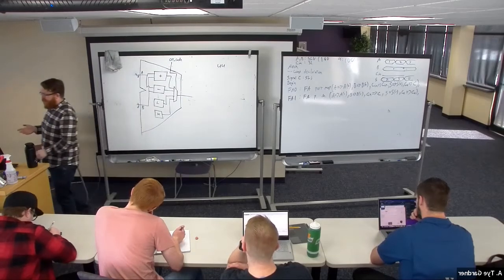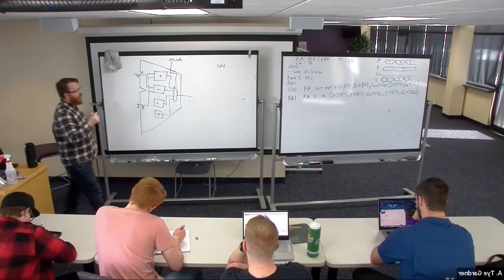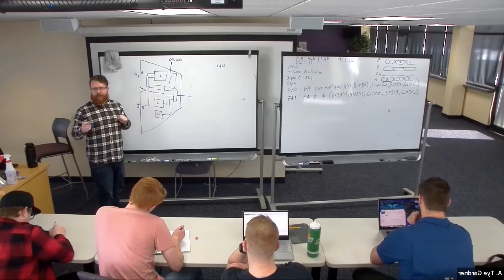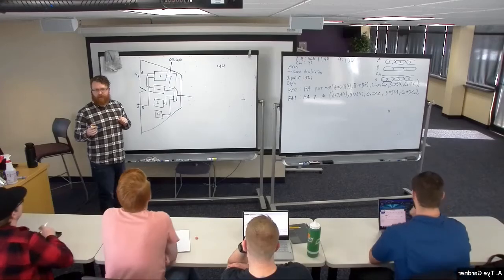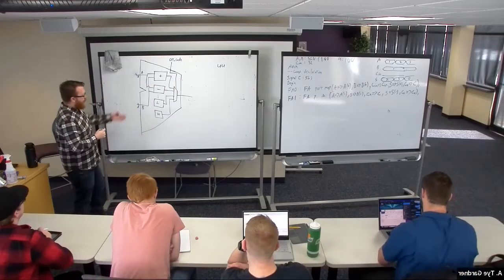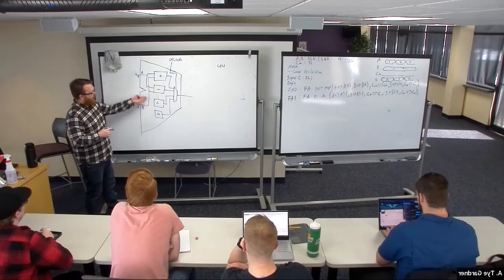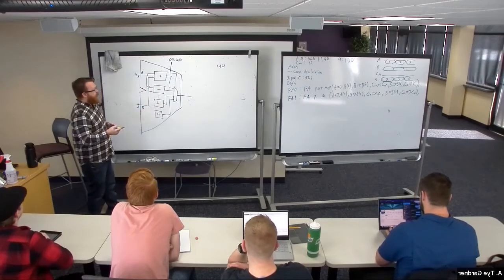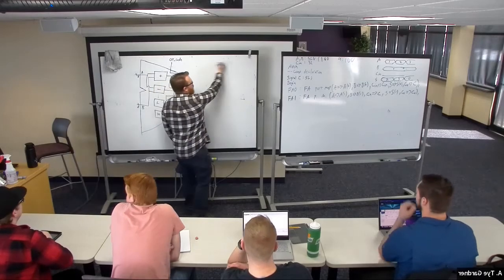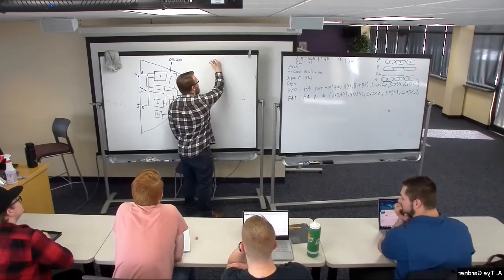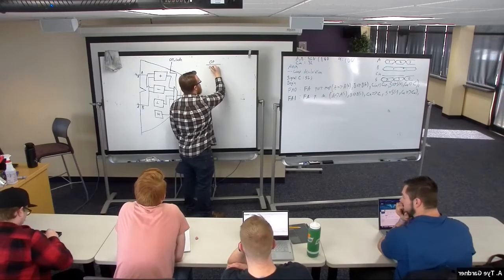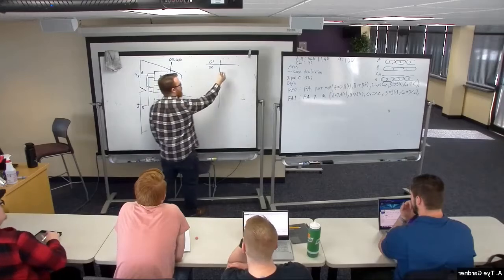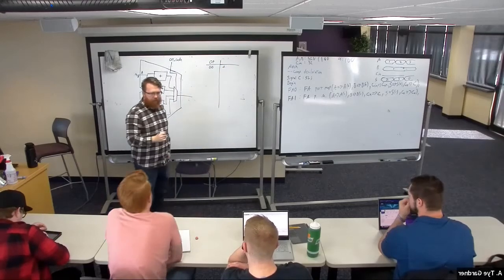Now, these opcodes are kind of interesting because we could think of them as a list. Let's say we're only using these 4. How big does my opcode need to be? 2 bits. Yeah, because 4 inputs, 2 bits. Well, if I have a 5th one, now I need 3 bits, and some of the opcodes might not get used. So I could say something like, when opcode is 0, 0, then I need to add.